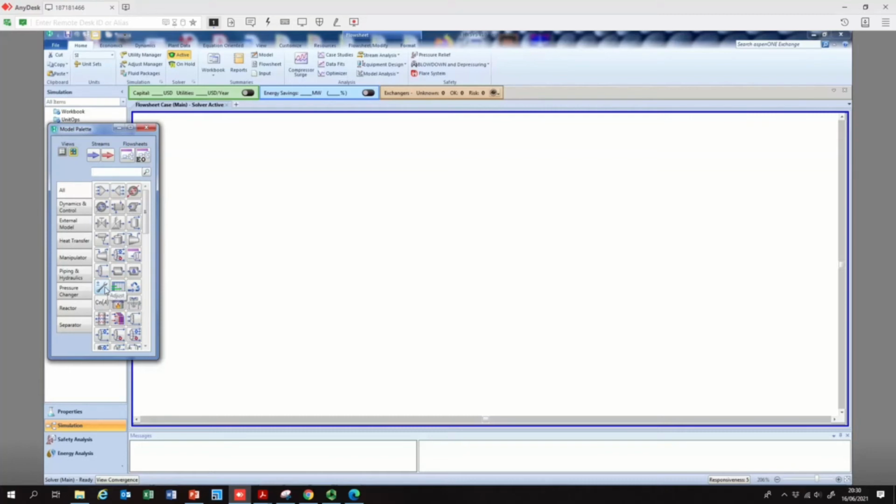So if you don't know the volume of my reactor, but I know the residence time in order to achieve some particular conversion, say 90% conversion can be achieved if my residence time is say 1 hour, then what could be the volume? And if I know the flow rate of my reactants that should enter the reactor, then from that I can calculate the volume. I will show you how to do all these things while developing the process flow sheet.